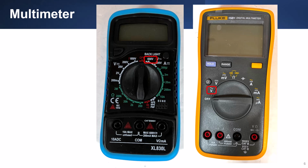If I was measuring voltage in Europe, where I expected 240 volts AC, I would select 600 volts. If you don't know what the voltage to expect, always go to the largest setting and dial it down as needed. For the Fluke model on the right, I would just select AC voltage since it will auto-detect the voltage. If I was measuring the voltage from a power supply, I would not expect more than 12 volts. Therefore, I would use the 20 volts DC on the left and DC voltage on the right.